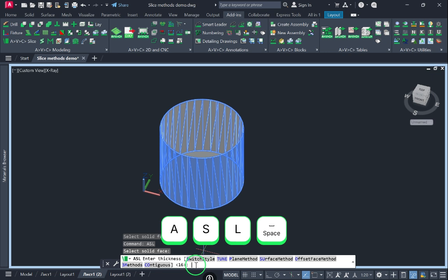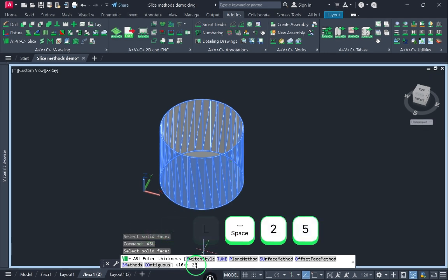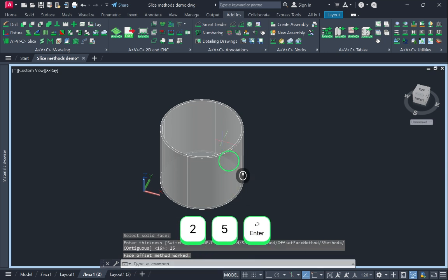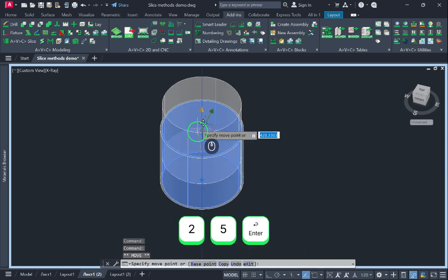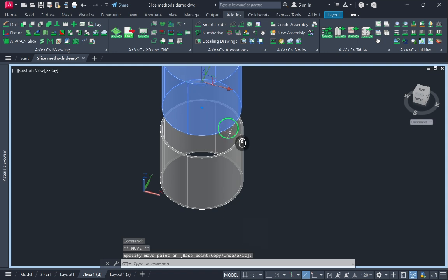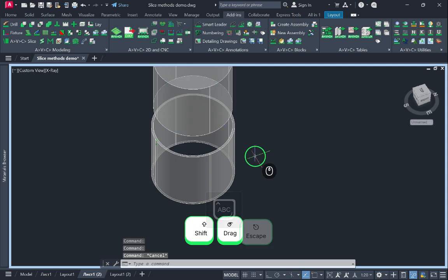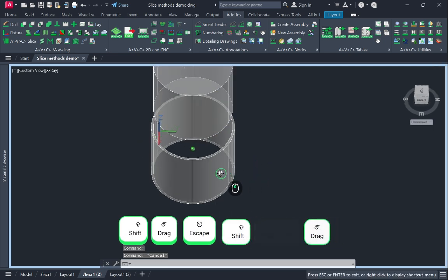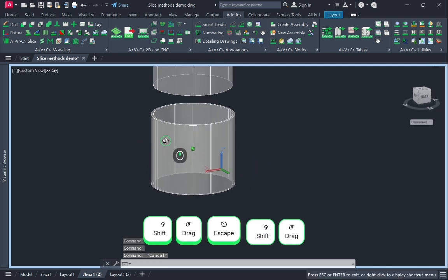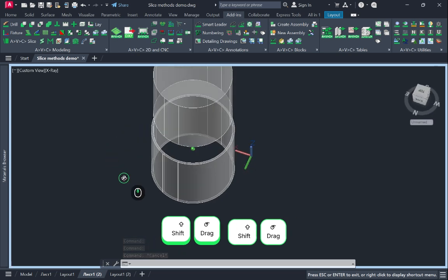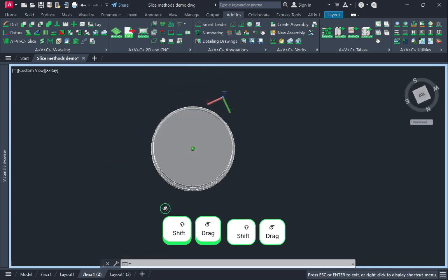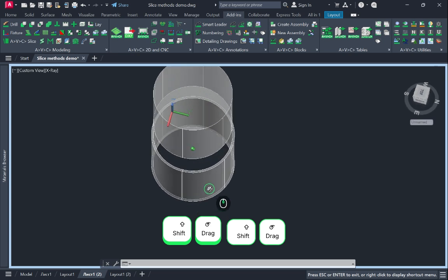One useful feature worth mentioning right away is presets. You can save any settings and switch between them instantly. Now I simply confirm the command. Done. In a single operation, a regular solid becomes a thin-walled shell with the exact thickness I specified. No extra construction, no helper geometry, no unnecessary steps. And it works not only with simple shapes, but also with complex objects of almost any geometry.